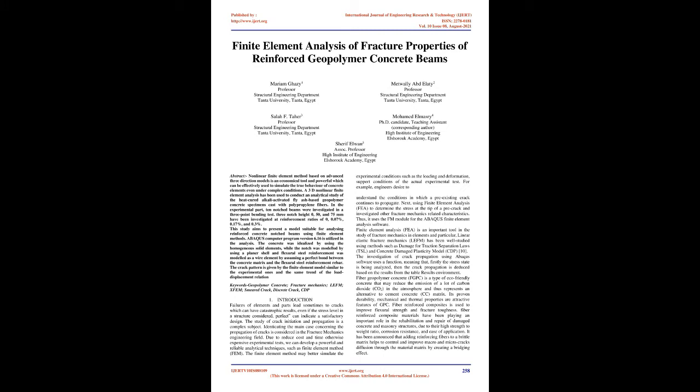methods. Abaqus computer program version 6.16 is utilized in the analysis. The concrete was idealized by using homogeneous solid elements, while the notch was modeled by using a planar shell, and flexural steel reinforcement was modeled as a wire element by assuming a perfect bond between the concrete matrix and the flexural steel reinforcement rebar. The crack pattern given by the finite element model is similar to the experimental ones, with the same trend of the load-displacement relation. Keywords: geopolymer concrete, fracture mechanics, LEFM, XFEM, smeared crack, discrete crack, CDP.